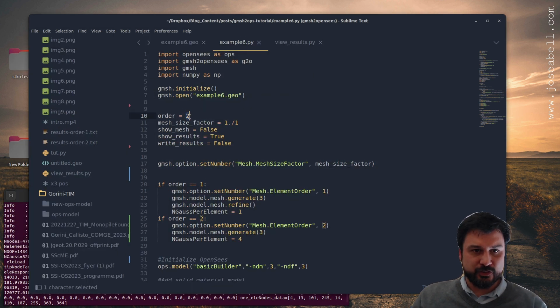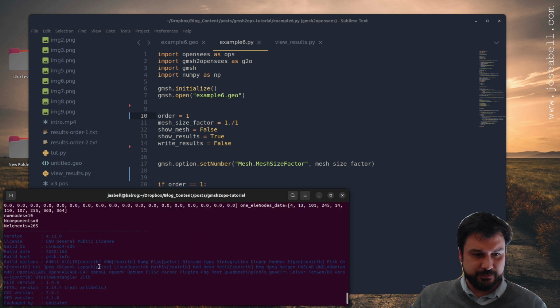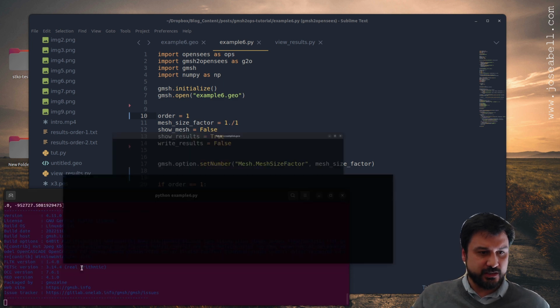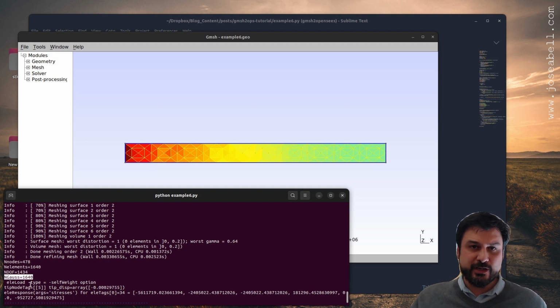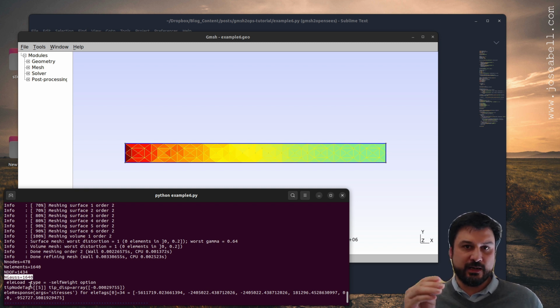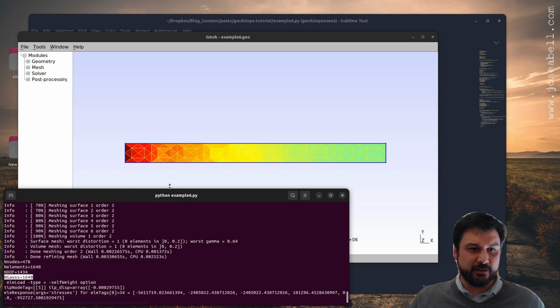So if I go back to first order for this same mesh discretization size, I get a really bad prediction, 29, and I have about double the number of Gauss points. If you're using a nonlinear material, that's really important because at each Gauss point, the constitutive, for example, plasticity computations, which are highly nonlinear, highly iterative, that's where they occur, and the more Gauss points that you have, it's going to spend more time there. So if you're doing nonlinear, you're going to want fewer Gauss points, and second order meshes actually get you that.